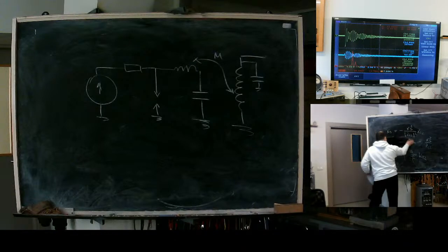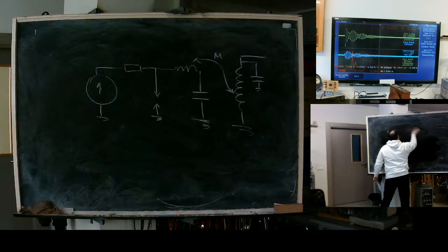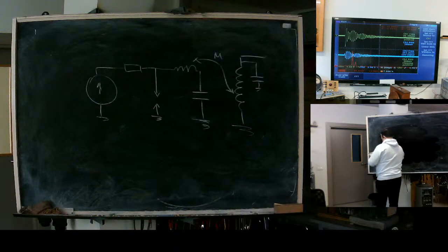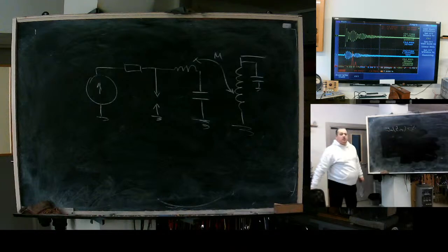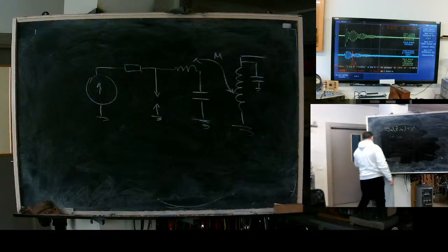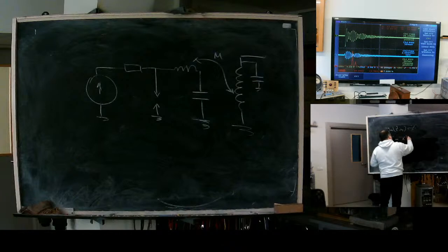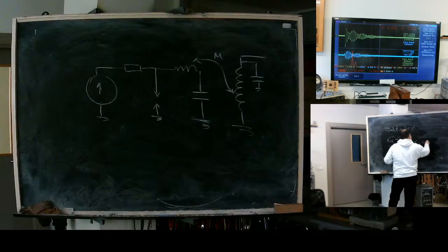Coupling frequencies. To find the coupling frequencies, we can solve for the imaginary part of the input impedance being 0. This will yield us resonance frequencies. So we will need to solve minus XS squared divided by Z squared plus X equals 0.